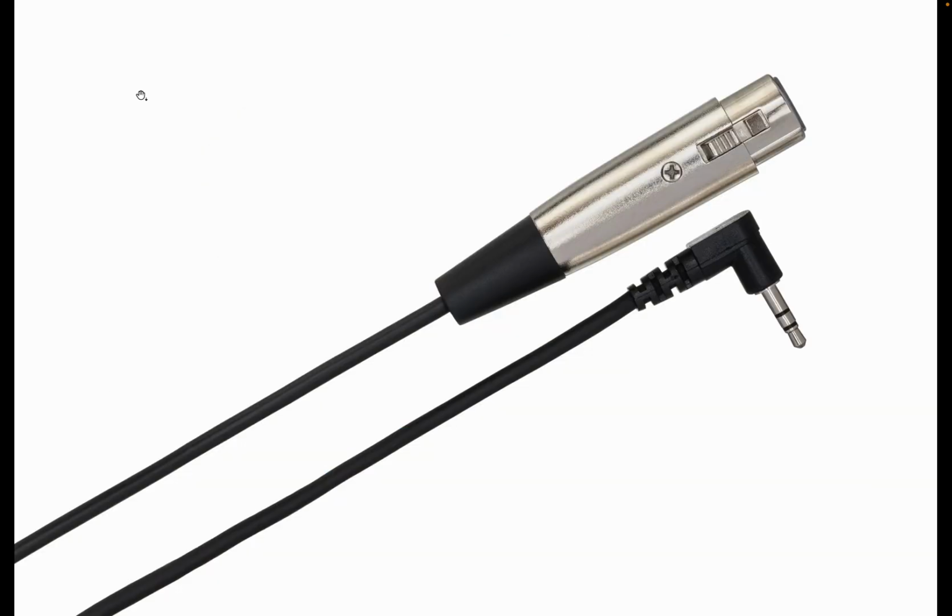There are lots of different adapter cables. Okay, this one happens to have the XLR on one side and then a standard 1/4-inch or 3.5 millimeter connector on the other side. The challenge with these is they don't tend to provide phantom power because they were never designed to actually send power to the microphone. So like the one on your computer, which is a 3.5 millimeter or a 1/4-inch adapter, they aren't designed to send that power that the microphone needs. And so you end up having to also provide it with power some other way.